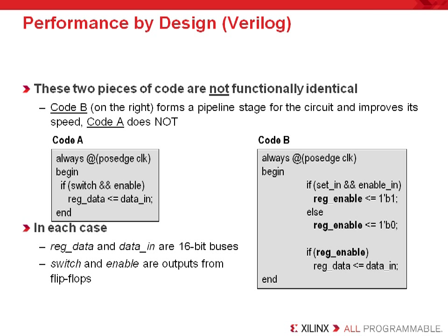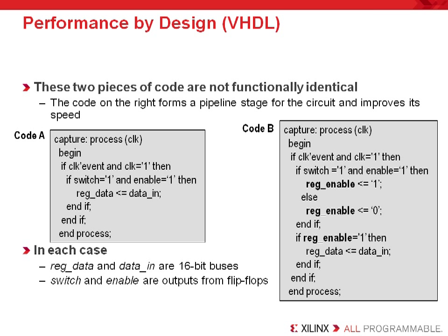Likewise, this kind of code can be used to add a register to a synchronous set or reset. So don't be reluctant to use this. In fact, many of our best designers do use this technique. Likewise, here is the same functionality built into a VHDL example. The key is to have a separate if-then statement to build the enable signal.